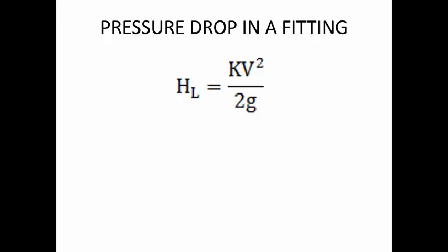Assume that your pressure losses are 20 bar. Now what happens? Your pump can generate only 100 bar pressure, but by the time it reaches the actuator, 20 bar of pressure is lost, so only 80 bar pressure is going to reach the actuator.